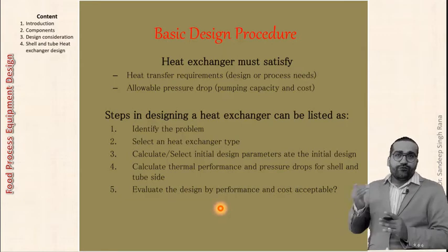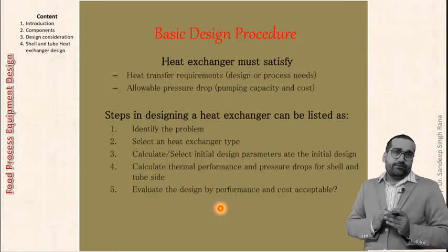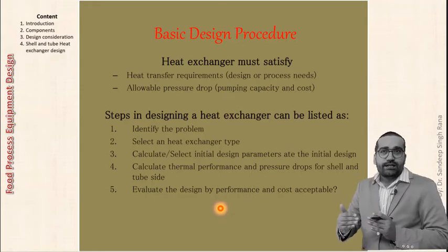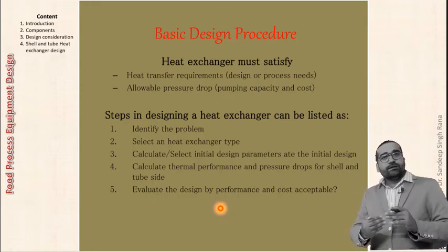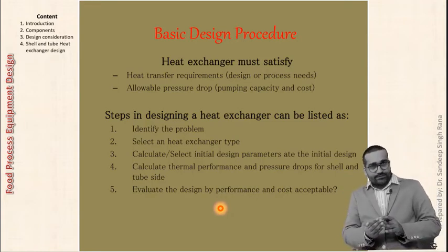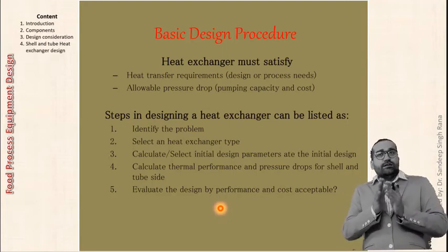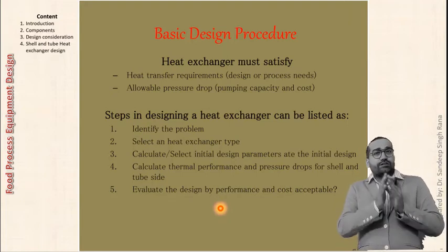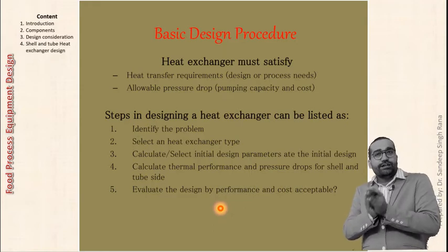If that is not fulfilled, then we will go to step 3 again. We will calculate the parameters again. Then we will calculate the thermal parameters again. Then again we evaluate it. So this is how we are basically going to design a heat exchanger. In this case, we are going to design shell and tube type heat exchanger.